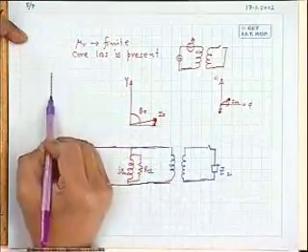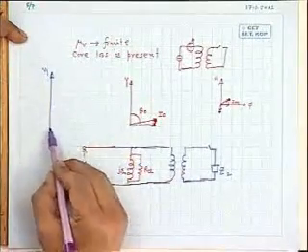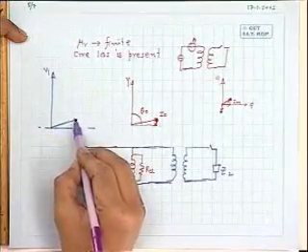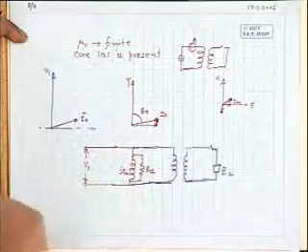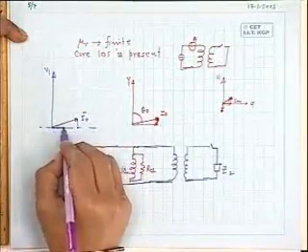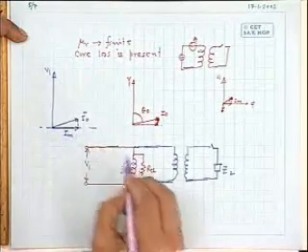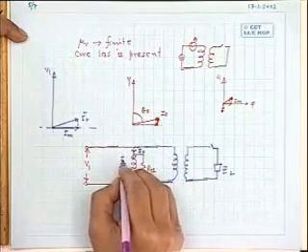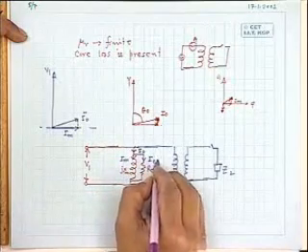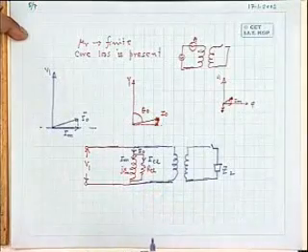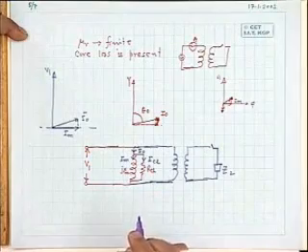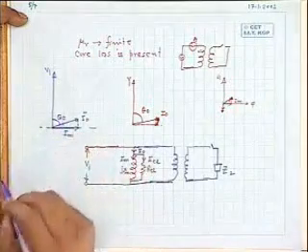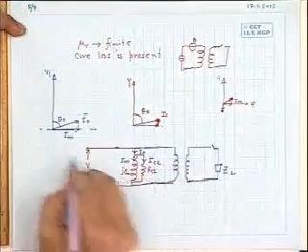Okay, so what will be the phasor diagram now? This is your supply voltage V1. The total current drawn from the supply during no load test is I naught. This I naught will have two components: the magnetizing component Im, magnetizing current, and ICL, the core loss component. CL stands for core loss component of current. It is the real power drawn from the supply, that is ICL into V1, and this is your no load power factor angle theta naught.